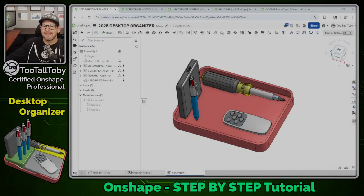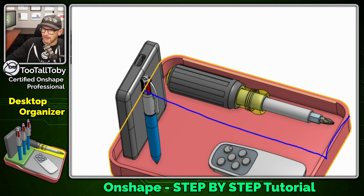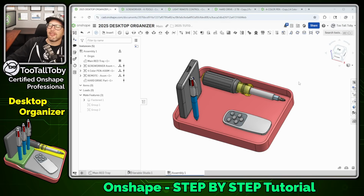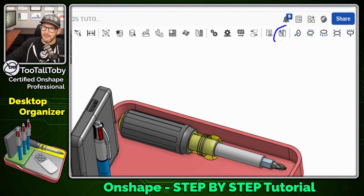So currently we can see that we've got these 3 tabs at the bottom: the part studio for the main red tray, our variable studio, and our assembly. Now we're going to choose to create a new part studio so that we can create the block for the screwdriver. But we're not going to do it down here. We're not going to go plus and then create part studio. Instead, we're going to use this icon here.